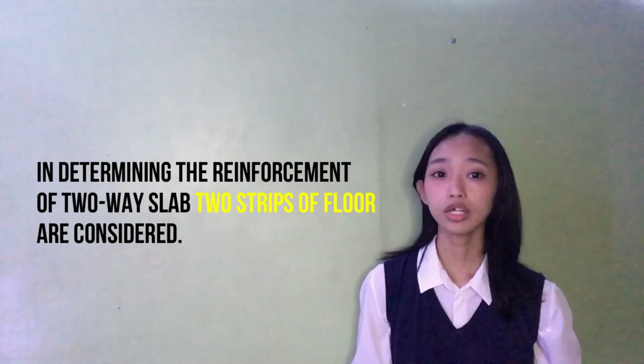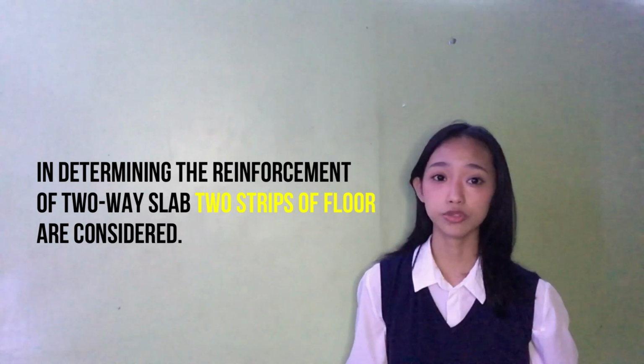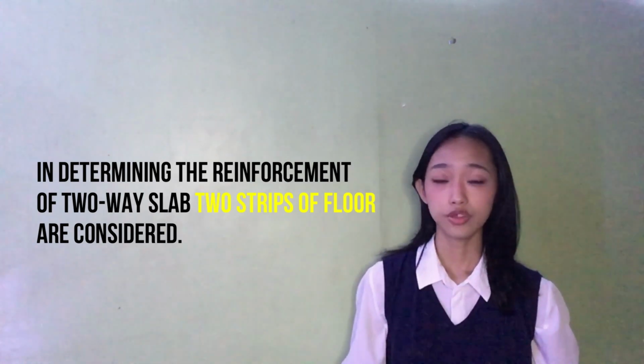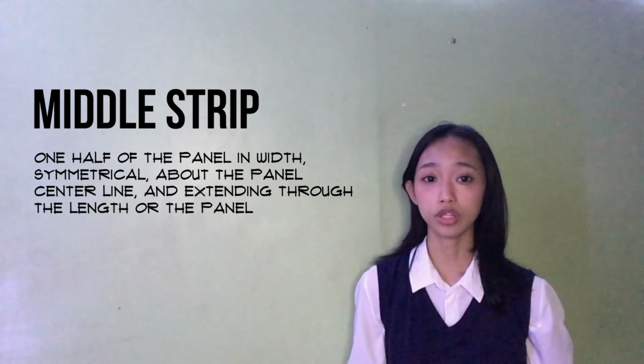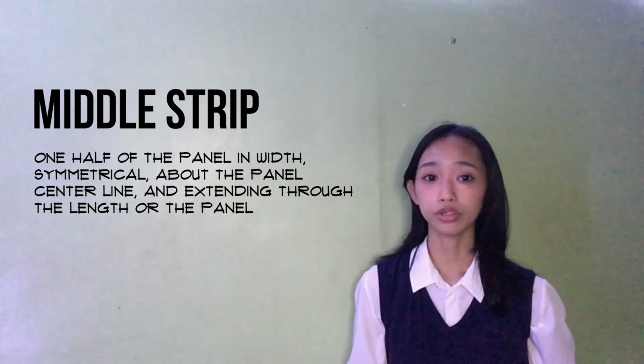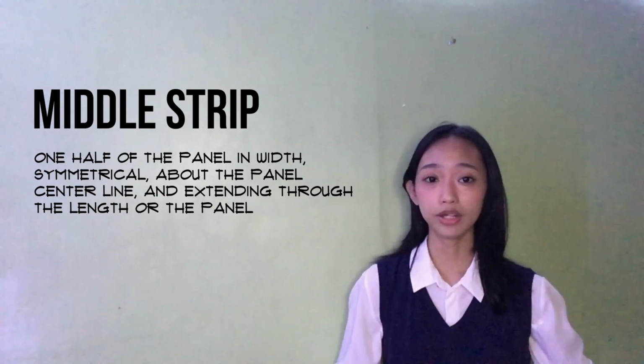In determining the reinforcement of a two-way slab, 2 strips of floor are considered. The first one is the middle strip. The middle strip has 1/2 of the panel in width, symmetrical about the panel center line, and extending through the length of the panel.